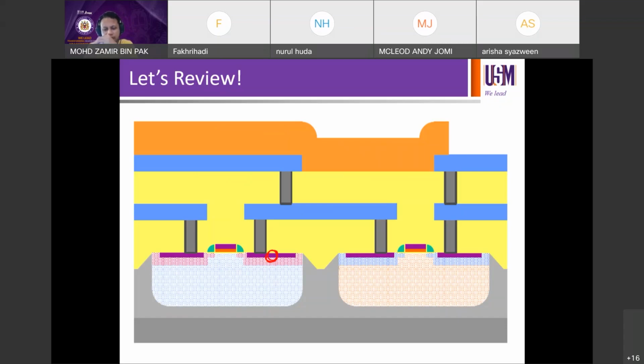Contact, be more specific. Is it the contact layer? It provides ohmic contact, okay? Be more specific, I say. It provides ohmic contact between your device and the metal contact. Your metal contact in this case is the plug, tungsten. Tungsten plug. This is your contact, the gray area is your contact. It's the plug, connecting between the device and the metal. Right? Okay, so titanium silicide.